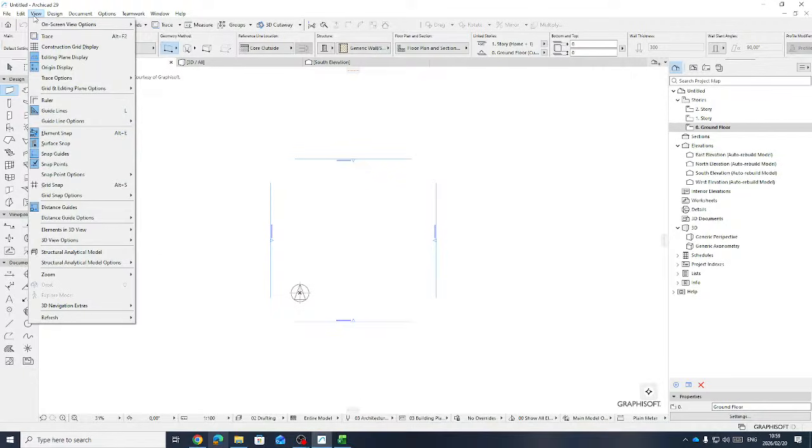Okay. If you just look up, you see there's a downstand beam. Sorry, those of you in your studio downstairs, just look up and look at all the service reticulation. You have to put services in a zone. They get zoned in. So that's excluded from the floor to underside of ceiling height. Typically, there will be a suspended ceiling here. That height needs to be a certain height. Then you need to provide a service zone for all your services run. And then, because there are beams here, we have to exclude that because we can't take the services through the beams. You're not allowed to punch holes into the beams. So everything has to run underneath the beams here.